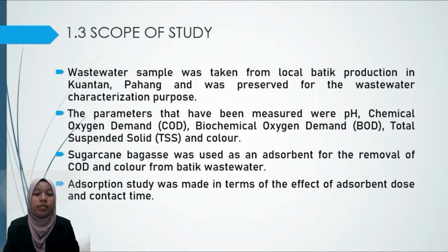Wastewater sample was taken from local batik production in Kuantan and was preserved for the wastewater characterization purpose. The parameters that have been measured were pH, COD, BOD, total suspended solid, and color. Sugarcane bagasse was used as an adsorbent for the removal of color and COD from batik wastewater. Adsorption study was made in terms of the effect of adsorbent dose and also the contact time.